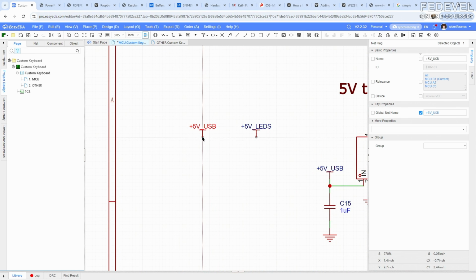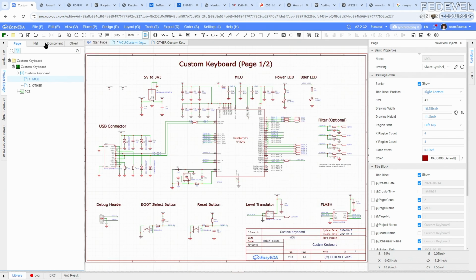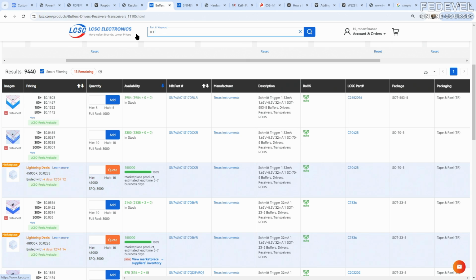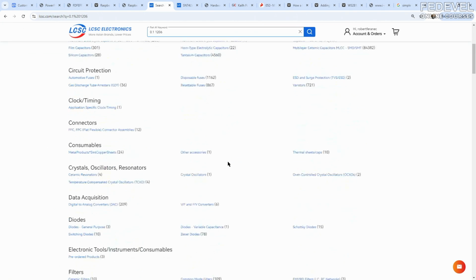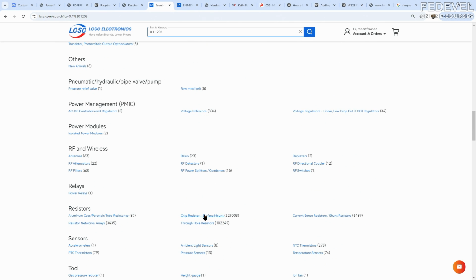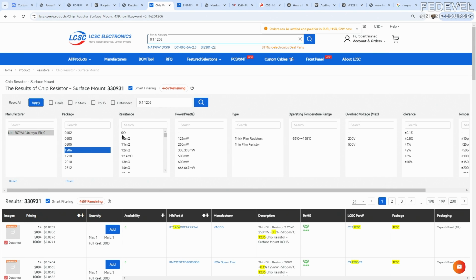Theoretically you can use a 0 ohm resistor, but I'm not going to, because it may be useful for a little bit higher currents to use a small resistor like a 0.1 ohm resistor. Again, some people may be asking why. It can help to keep the quality of the power rails.